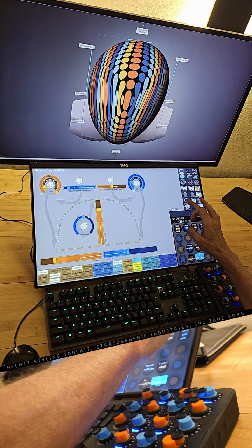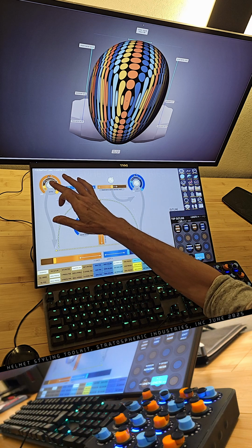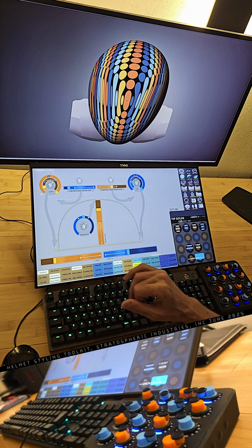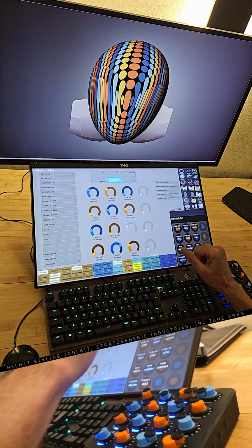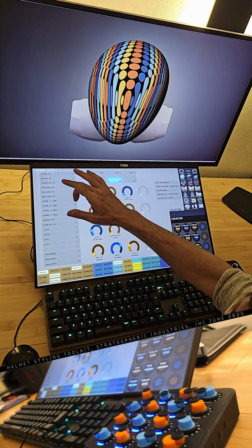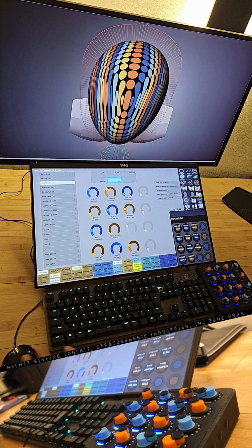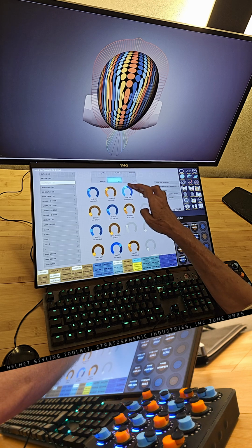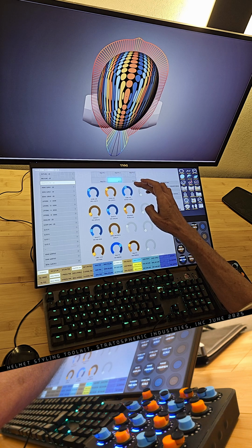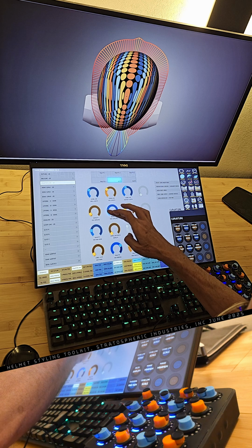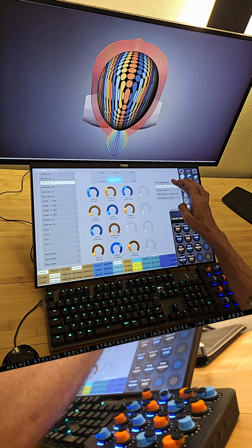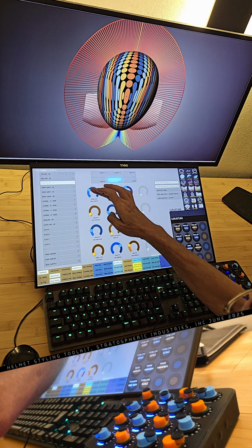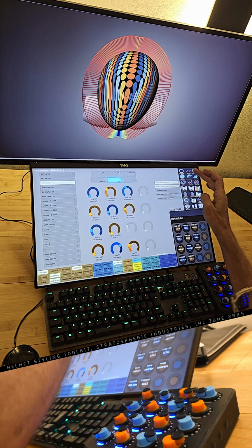Let's go to final. Let's take a look at one more aspect here. Let's turn off the pins, just for eliminating the visual clutter. This is the curvature analysis. So this is the curvature of the top of the helmet. It is viewable in color with different thickness comb lines, with different densities, with proportional spacing, with inverted comb magnitude, with minimum and maximum comb lengths for visibility,